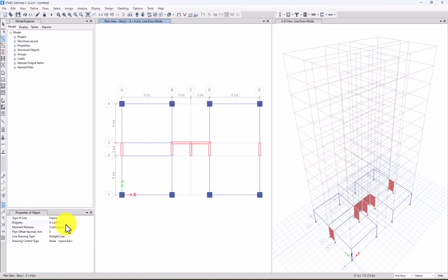We use these techniques, using this one and using beam again, 6 meters. Oh, that was use this one. Remember to do the center, otherwise you will disconnect it. So now it's okay. We need a lintel beam here, so I can use the same things, no problem. 3 meters, 3 meters. So it's okay. If I go to this beam, it is still okay.